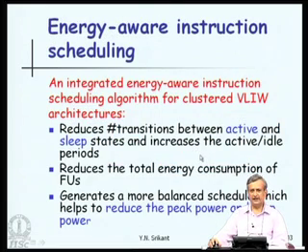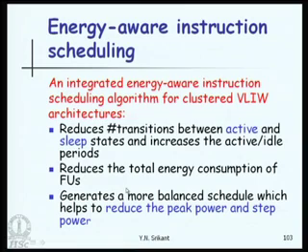An integrated energy aware instruction scheduling algorithm for clustered VLIW architectures is what is proposed. It reduces the number of transitions between active and sleep states and increases the active and idle periods, as I mentioned before. It reduces the total energy consumption of the function units and generates a more balanced schedule, which helps to reduce peak power and step power as well.